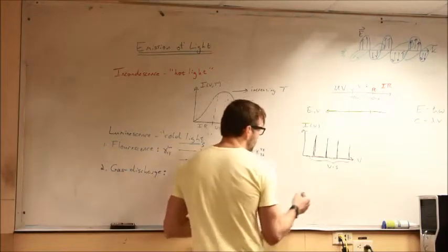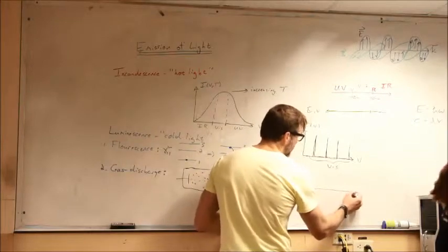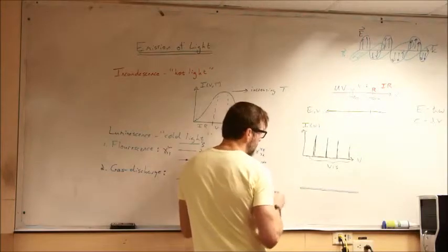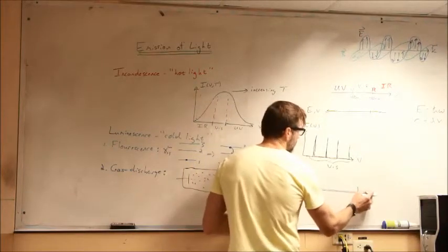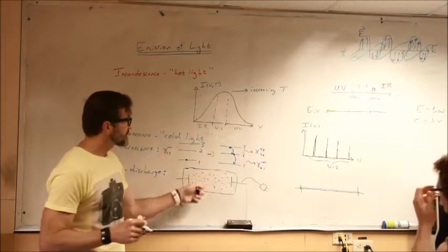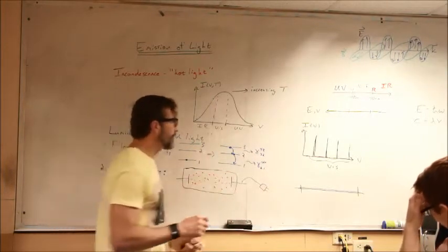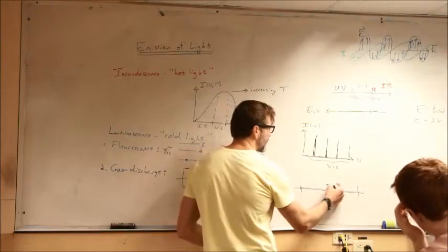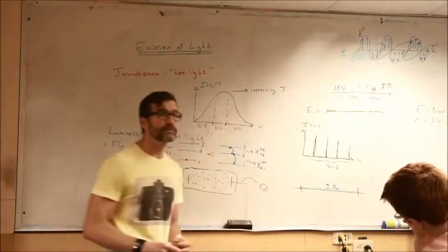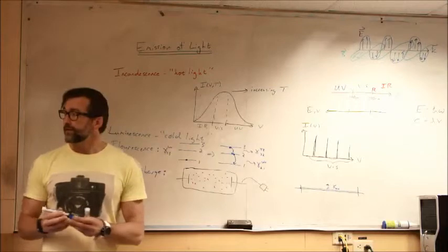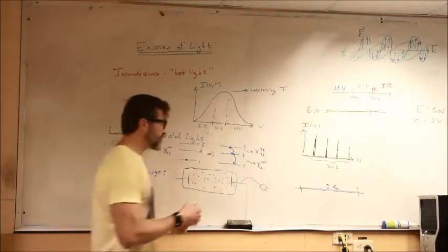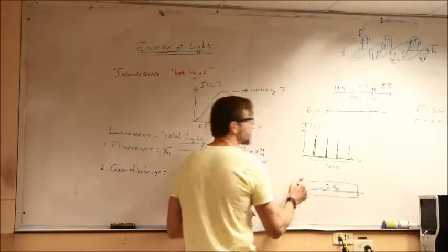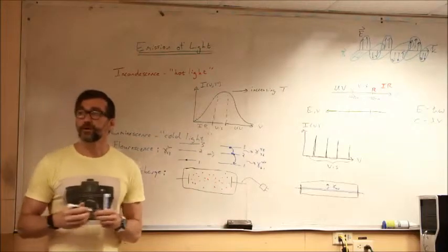So in an overhead compact fluorescent lamp, what we actually have is a thin tube of something like mercury vapor, and it is connected to a cathode and an anode. So we have a gas discharge tube, and when we turn the overhead lamp on, this thing will start emitting light, but that light is going to be in the form of ultraviolet photons, okay, high energy photons. However, that very thin gas discharge tube is surrounded by the larger tube, which is the thing you actually see, which has a phosphor coating on its interior.